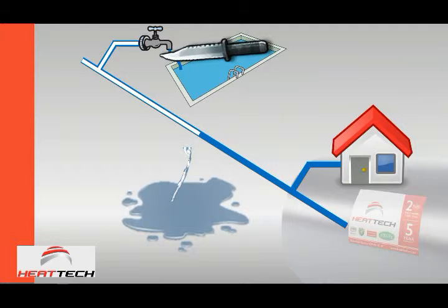In other words, by cutting the line, you allow air to be sucked into the line, and it will settle at the lowest point, at the point where the leak was, because there's nothing that drives it further. And that is much safer than having the dirty water inside the line.